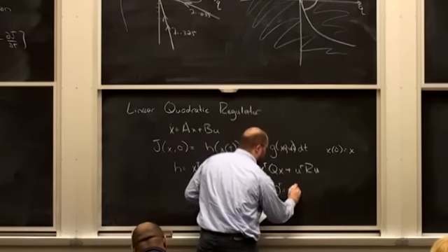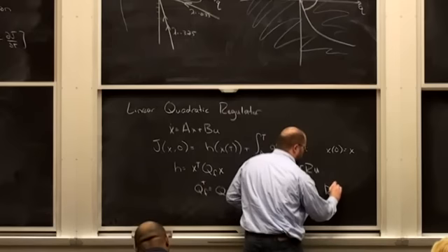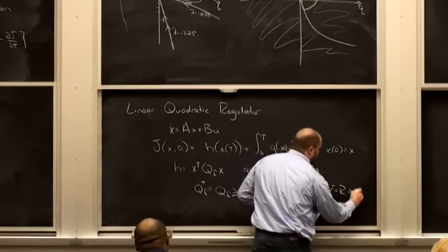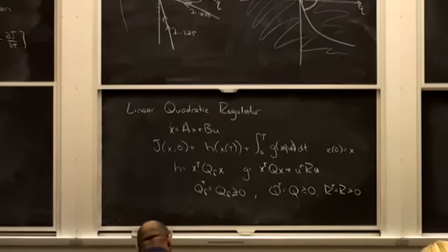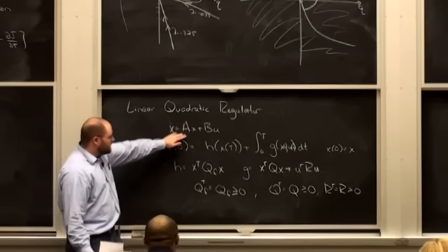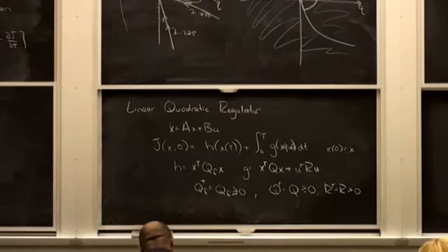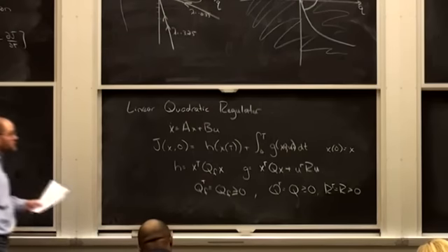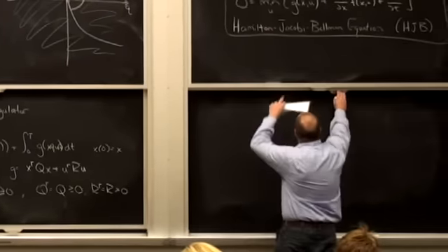Q transpose equals Q greater than or equal to 0, and R transpose equals R. That one does have to be positive definite. Okay, here's a pretty general linear dynamical system, quadratic regulator cost. To satisfy the HJB, we simply have to have this condition met, right?